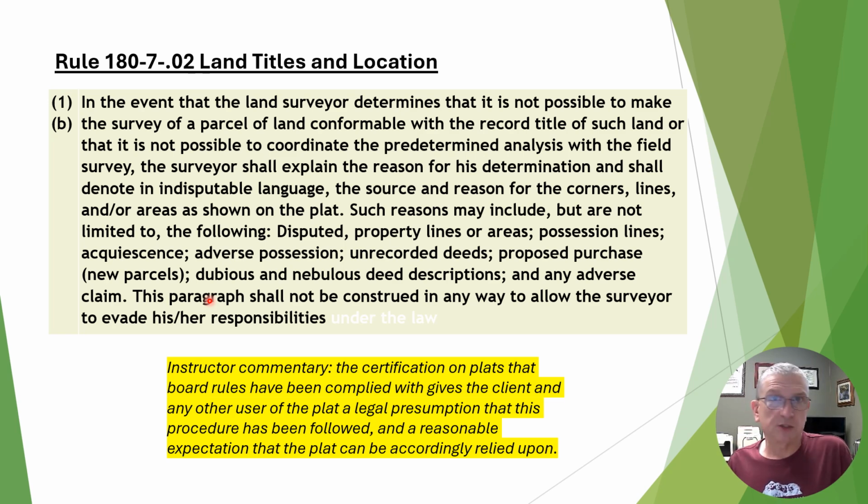Junior and senior rights is one application that's kind of a gray area as to, do surveyors have the ability to move a property line? Well, a senior right or a senior line is a property line. A junior line that's in conflict is just really a mistake. So if we hold the senior line, then we are just adhering to proper title boundaries after we've done the analysis of the research. But we cannot just ignore where the junior line is, because somebody's bought to that.